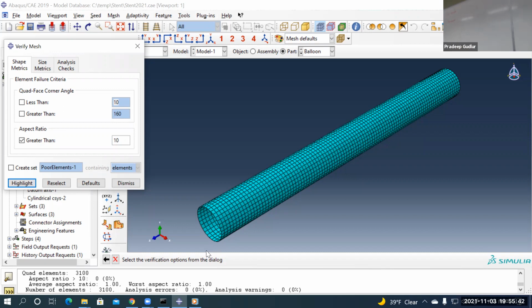in this direction, say whatever this direction is, Y, say this is X. In the X direction, your field is changing. Say temperature problem I'm solving. In the X direction, I have temperature varying drastically, but in the Y direction, the temperature is not varying at all because this element edge itself is very small. It won't give good results. You can't trust the results if your aspect ratio is, say, greater than 3. So you want proper proportions for each element.